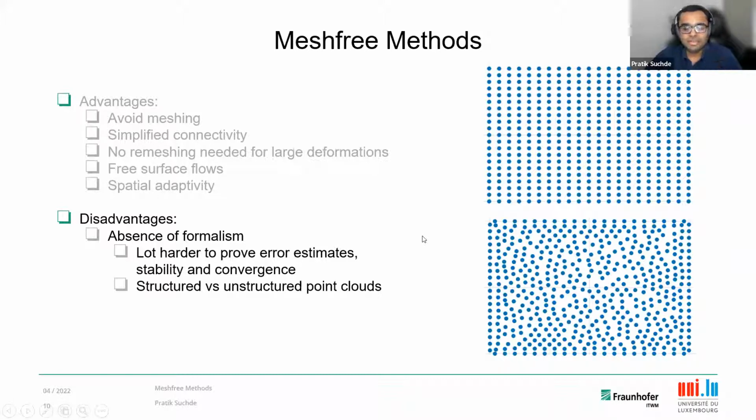It's really hard to prove things in mesh-free methods. In most cases, people have been unable to prove error estimates, unable to prove convergence or get bounds on your solutions and things like that. While that is slowly changing, and people are slowly trying to do this in mesh-free methods, it's still far, far behind what you can do in finite elements or finite volumes.